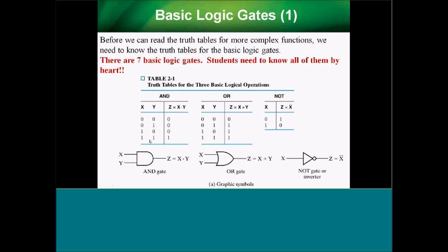And I tell them it doesn't matter, and this is an important aspect that you see in Boolean algebra, if you have 15 variables in there, X, Y, Z, P, D, Q, whatever. If one of those is 0, that gate is 0. It wipes out the whole thing. That's a very powerful concept that they need to know, and it's very important in digital design: the concept of enabling and using AND gates in that way.